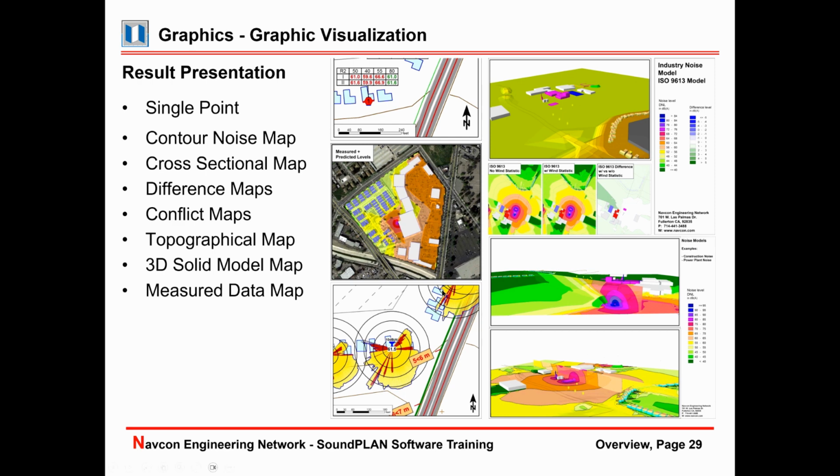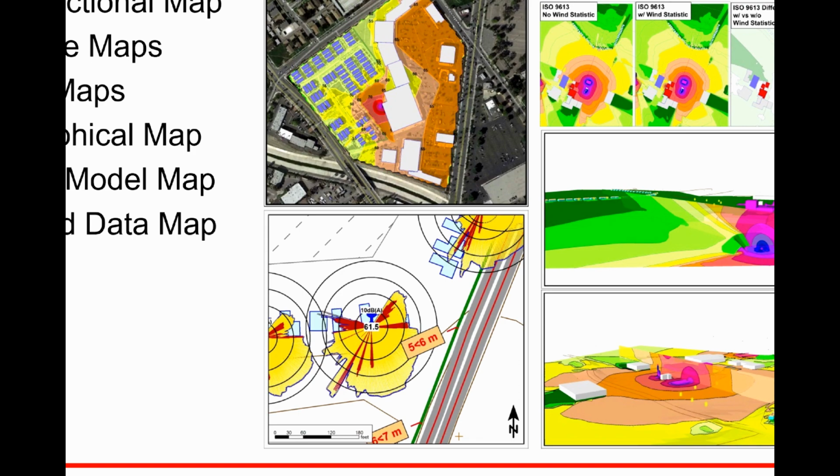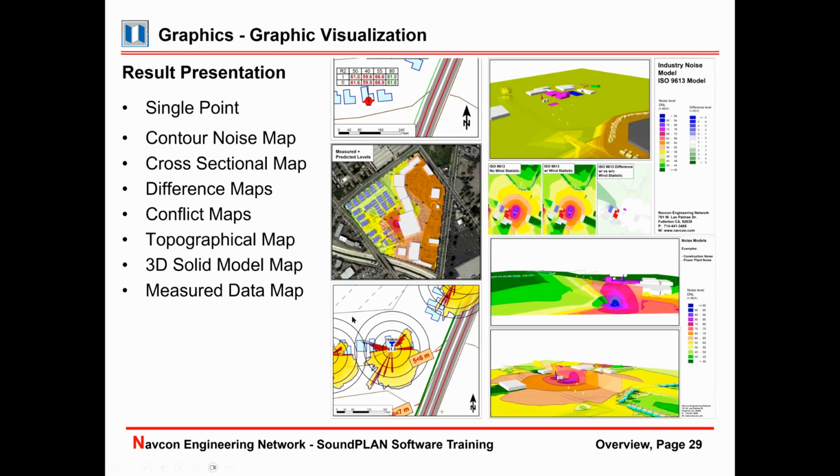There are also some results that can visualize the contribution, the sound level diagrams down here, bottom left, that give us the contribution. So each circle represents 10 dB. So we can identify the magnitude for each direction, and whether the contribution is direct sound, the yellow lines, or the red lines, which are reflected sounds.